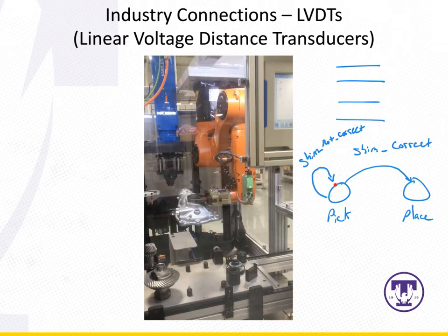Is it the appropriate size? No, no, no. And we'll stay here forever until we get the signal that we have finally picked a shim of the appropriate size, and we move on to the next state. So see the difference. We're not just going through a linear sequence of events, pick shim, place shim, and so forth. That's not it at all. We're going pick shim, and if the shim's right, we'll place it, but if it's not right, we're going to pick again. And it's not right, so we pick it again. So this is a state-driven situation, not a simple linear situation.